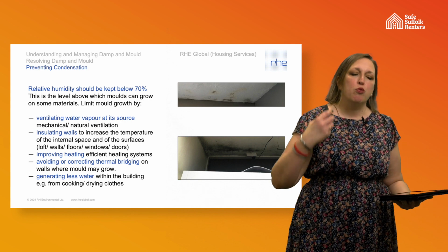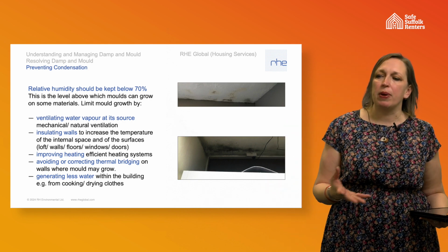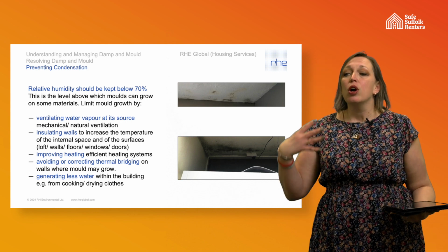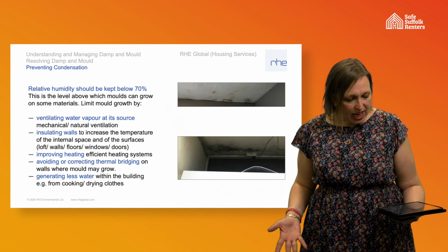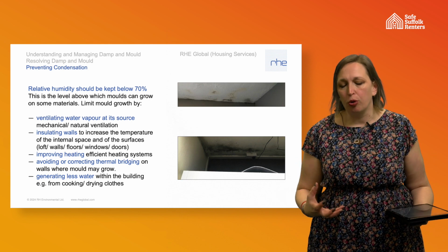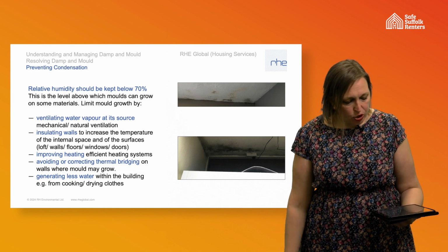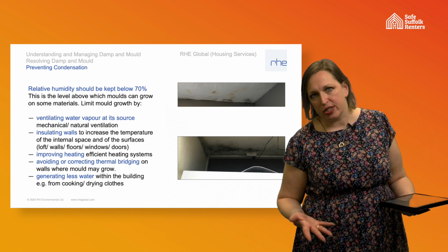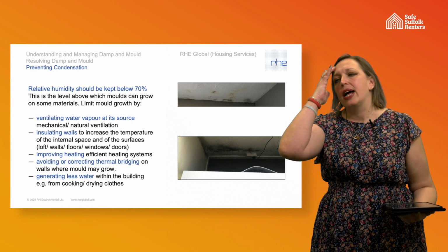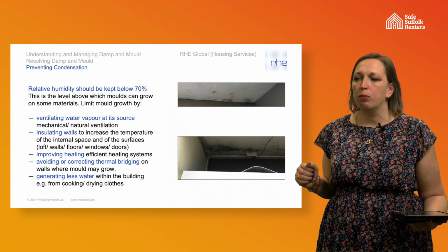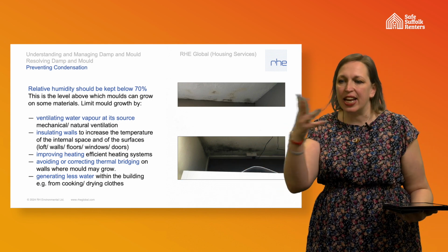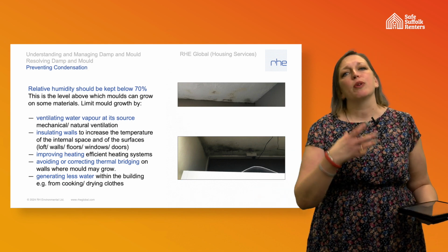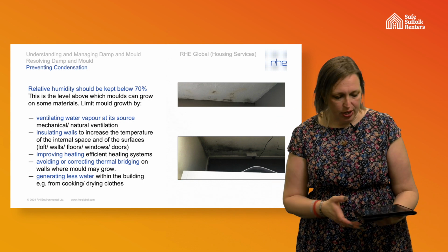We can talk to people reasonably, but we can't expect people to not bathe, to not wash their clothes and to not cook meals. Those are reasonable activities to undertake. It is a house, it's not an ornament. We need to live in it. So we can talk to people about, for example, making sure that you've got the extractor fan running when you're bathing and that the door's closed so our moisture-laden air isn't going throughout the house, it's staying in the bathroom and being extracted. But we can't say to people, take fewer showers. It's all about what's a reasonable approach within that dwelling.